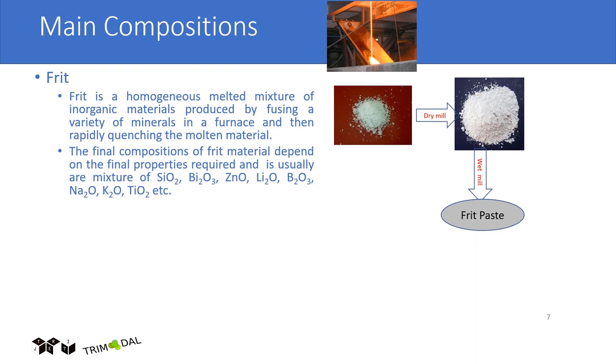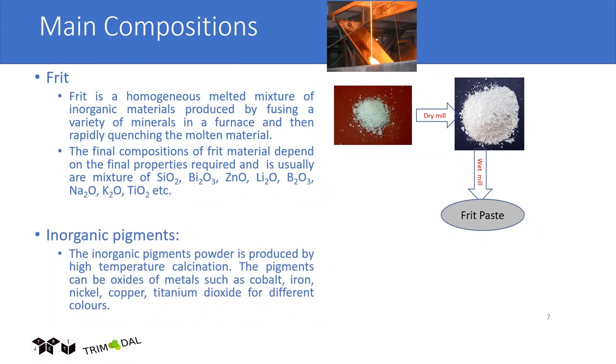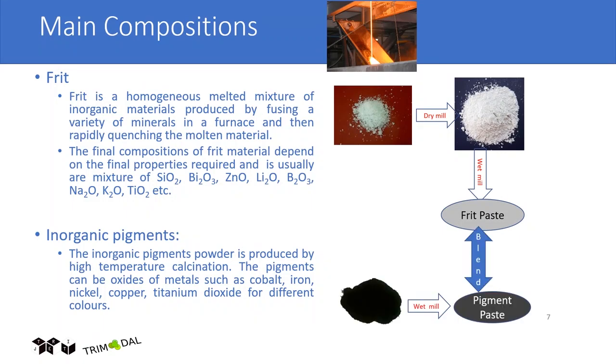Okay, and digitally, we now need to bring that further. So we need to wet mill it to a paste of below 1 micron size. That's the standard, even 2 microns. And then you have the pigment. These are fairly standard inorganic pigments you buy off the shelf. Again, these have a particle size of 3-5 microns. You bring it down to 1 micron. Again, you mill it, and then you blend these two together. You have a concentrate, and that gives you the concentrated ink, right?